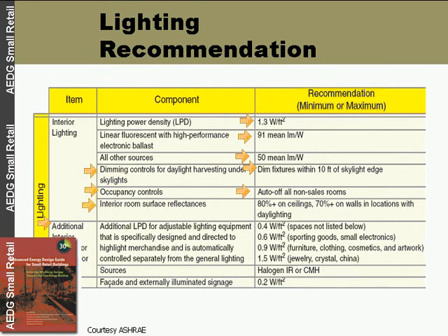There's a second section that's kind of hidden a little bit behind the cover of the retail guide that talks about additional interior lighting power allowances. And this was a big part of the retail guide: how do we deal with that? If we go back to the 99 standard, we'll actually see that there were recommendations for general accent lighting, and then there were recommendations for featured or fine merchandise lighting. And that was 3.9 watts per square foot for the fine merchandise and 1.6 watts per square foot for the general merchandise lighting.